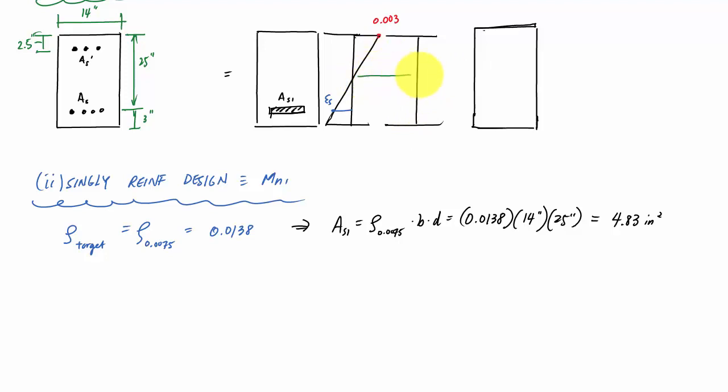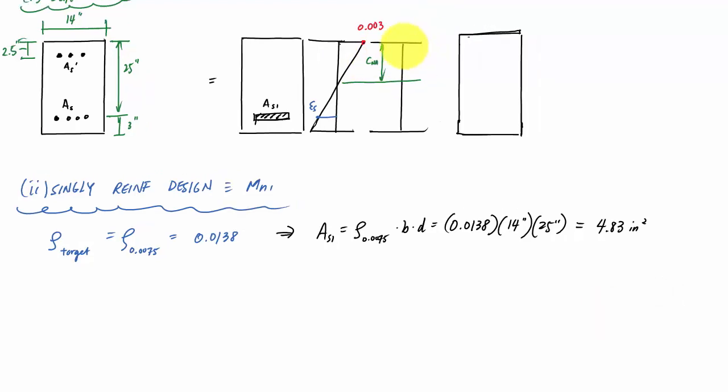There's some neutral axis depth, c_NA, and there's some equivalent stress block, a, and this is 0.85 f'c. I have a resultant Cc here, and then an Fy because it's yielded, and Ts1. Okay, and so do I know c_NA?